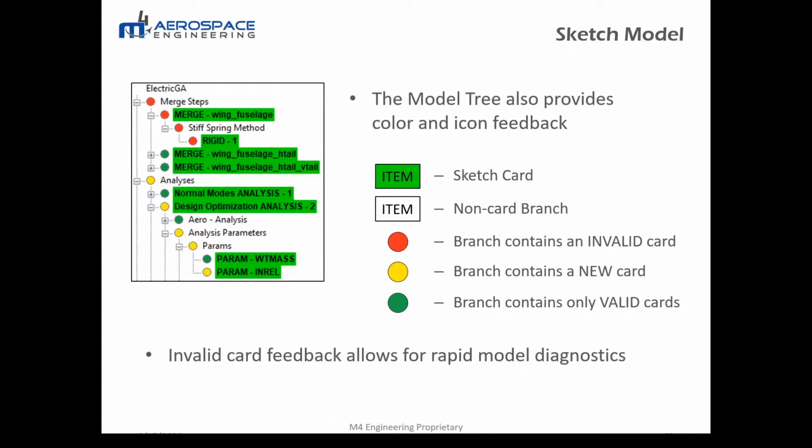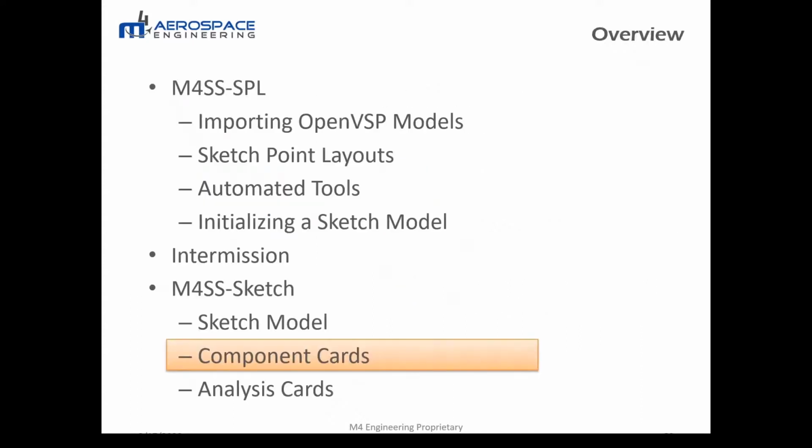And then finally, when all the cards are marked green and every desired sketch card has been added, then the model is valid and can be used to generate the finite element model. So now I'm going to go over some of the more commonly used component cards.